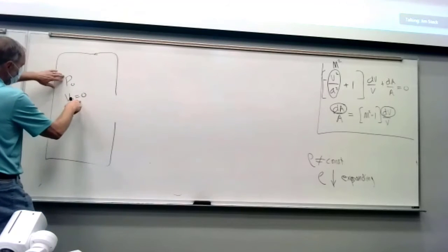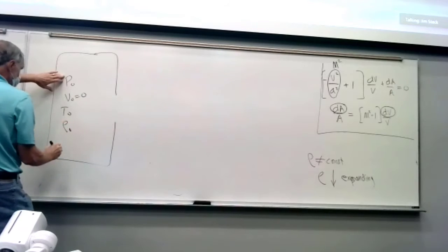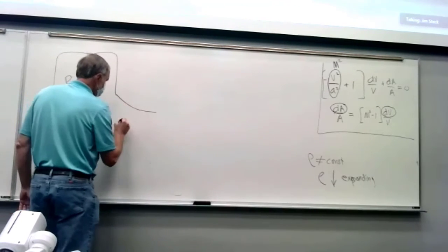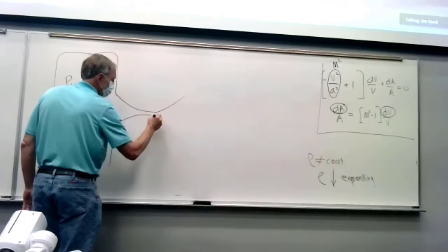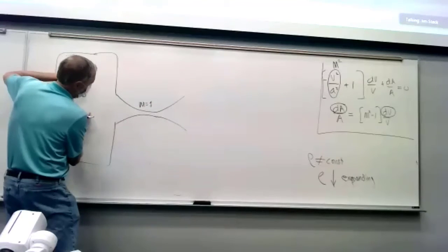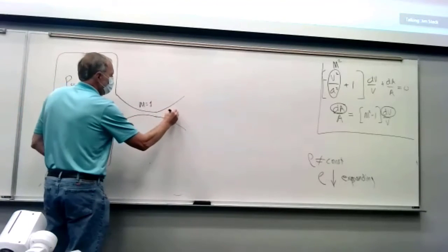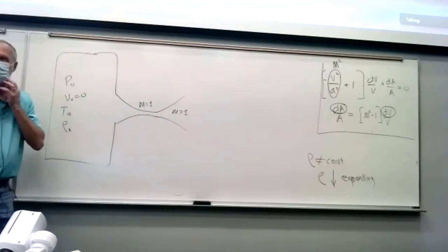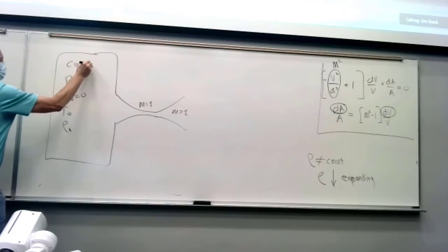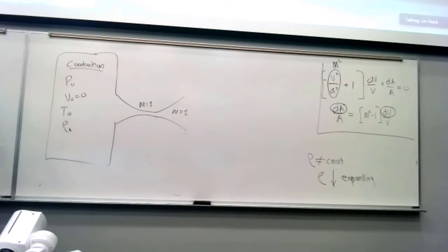The tank has velocity of 0, so this is stagnation temperature, pressure, and density. That means that's total pressure. It's just where the velocity is 0. And then you run it through a very narrow orifice. And this has to be small enough so you get Mach 1 here. So it has to speed up from 0 by going through here. You hit Mach 1, and you get supersonic flow here. So you can either pump up a tank or you can have combustion, like in a rocket, where you burn fuel, and all that energy goes into creating the pressure, temperature, and high densities.